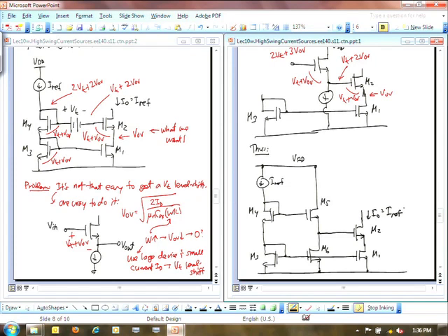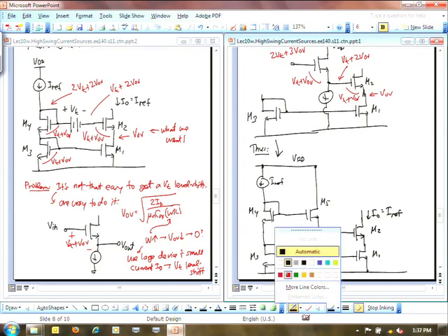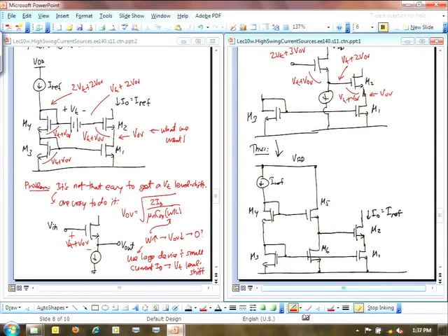Okay, so this now becomes a circuit that I've made, and you can see I've pretty much drawn what I have up here, except now I filled in the details as to how I'm generating the currents on this side with M4. And so again, I have a couple goals here. One of my goals is that at this node here, because it's before the level shift, I want 2 VT plus 3 VOV.